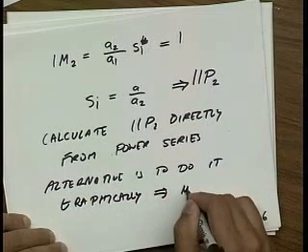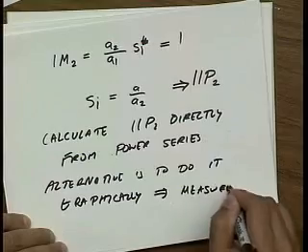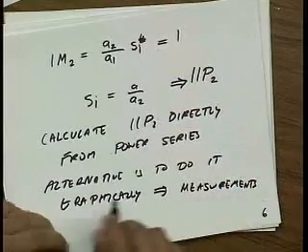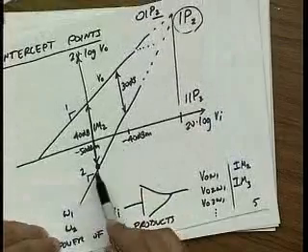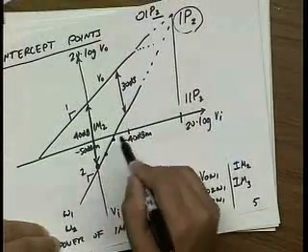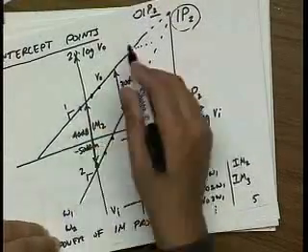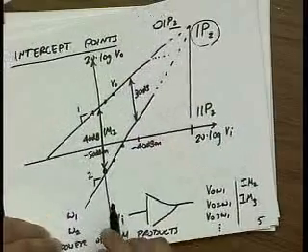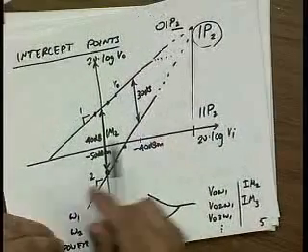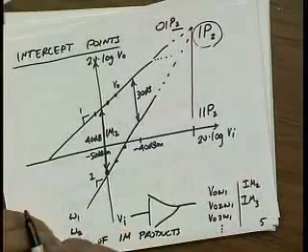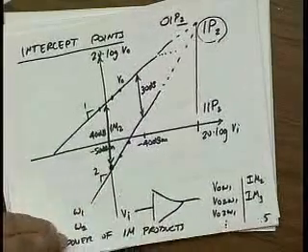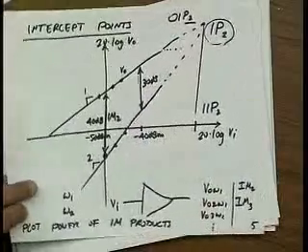And this is the way we do it with measurements. We typically will measure the IM at several input points, basically verify that the amplifier actually fits within these lines. We do that just to make sure we're not crazy. You know, maybe the amplifier is hooked up incorrectly, make sure the slope is right, and then you extrapolate to get your IP2 point. Okay?